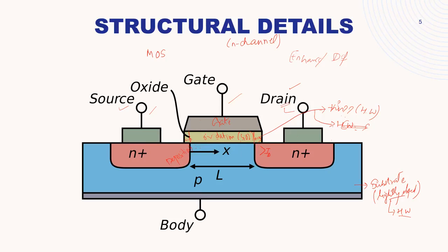We'll come to voltages now. So there are two important voltages of this N-channel MOSFETs, VGS and VDS. And one request, since we are not going to do everything for PMOS, the P-channel MOSFET, you can consider it as either VSG, VSD, or you can see it as a VGS mod or a VDS mod for PMOS.